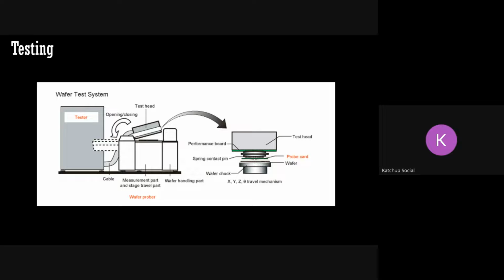There is a question: suppose clock tree synthesis has failed, which team will resolve this? Let's understand the meaning of failure. When you're doing clock tree synthesis, you're connecting wires to every part of the clock. So the meaning of failure is that the clock is not connected. Tools will automatically check that the clock is connected, and will issue errors or warnings when it is not connected. So the same place and route team will ensure that these steps are done properly. And then you do testing. Testing is very important.